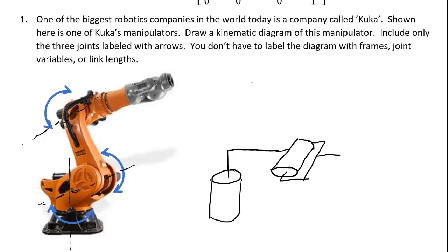When we're drawing in 3 dimensions, you can only draw lines that are going in a couple of specific directions. Anytime you want to show something going up or down, the line will be vertical. If you want to show something going right or left, the line should be horizontal. If you want to show something going away from you or into the page, the line should be at a 45-degree angle in the first quadrant like this. And if you want it to be coming out towards you, you want to draw a line that's a 45-degree angle in the third quadrant.